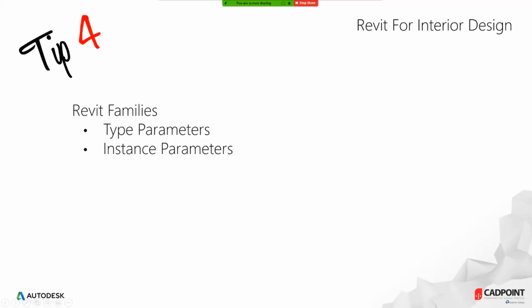Tip 4, Revit families. I would say this is really crucial for you guys to get your head around how families work in Revit. And families are a little bit like blocks in AutoCAD. Understanding Revit families, types, and instances is crucial to understanding Revit. When I'm training the Revit Essentials training course, this is the part that most people will have problems with or be confused about. Yet for those of us using Revit, it's become second nature to understand that.